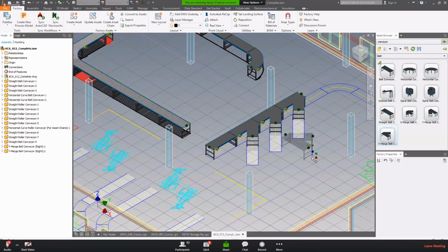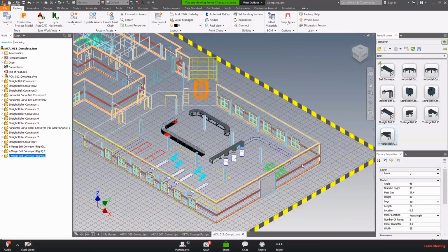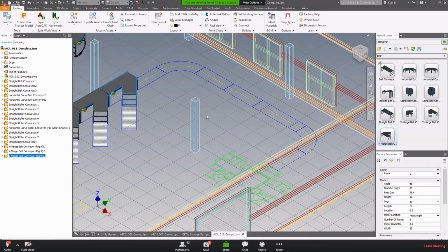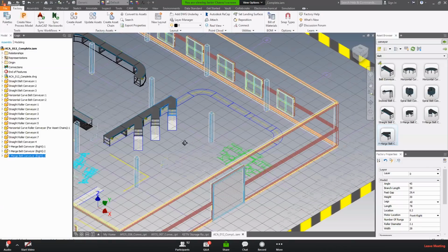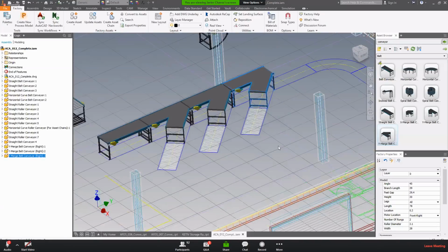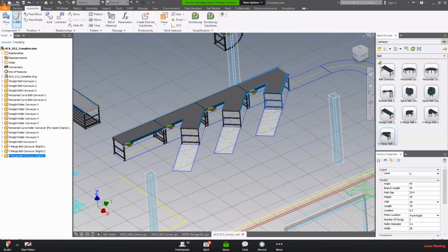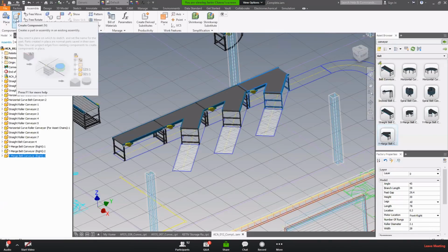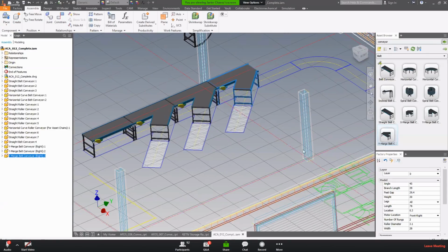Okay. So what we're looking for, and I can go ahead, is to build this whole facility out and utilize it with assets. I don't know if you noticed, but I didn't have to mate it to the floor. It simply behaves that way because of an asset publishing process that we're going to go through in a minute. With regular assemblies, if you just use the assemble tool and place components, you're going to have to use regular mate constraints. If you drag and drop from the asset browser, it's going to be a lot easier.